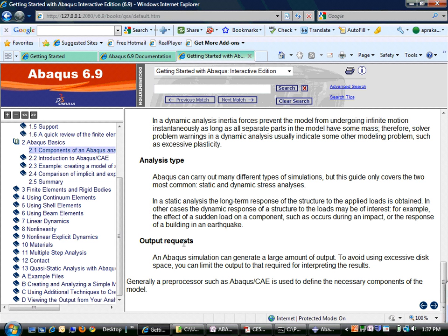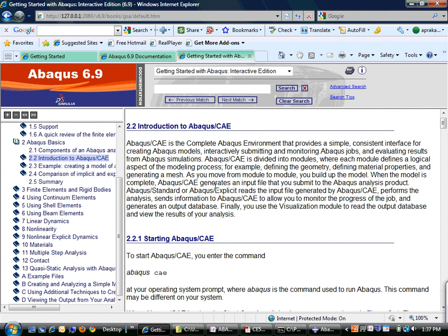In general, a finite element program can create a huge amount of data. At every Gauss point and every node, you can get multiple different variables that you might be calculating. So you have to choose the output requests carefully so that the output files don't just completely blow up in size.